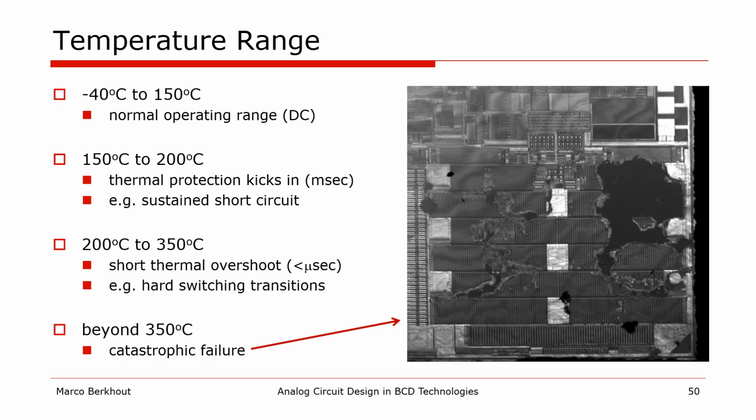This picture shows the remains of what used to be a 150 watt Class D audio power amplifier used in an application with poor supply decoupling. This actually caused an explosion in the lab with chunks of plastic from the package flying around.